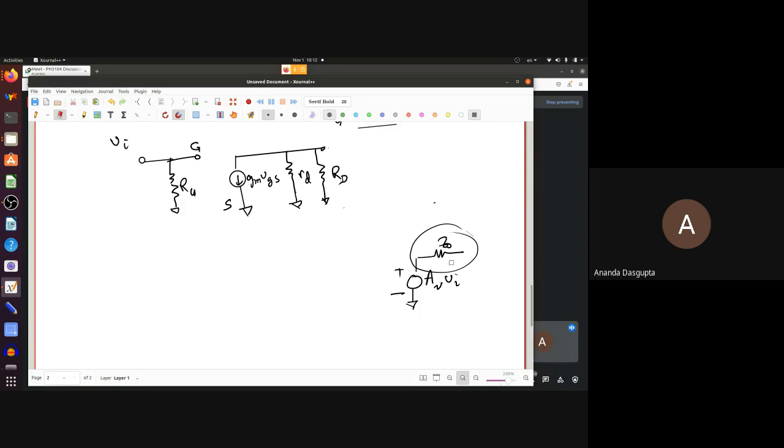Remember, this is just an effective circuit. It doesn't care what you have on this side. So you could also connect a voltage source here. If you connected a voltage source on this side, a Vx, some voltage source, and try to calculate the current Ix which flows in because of that, then Vx by Ix at Vi equal to 0 will give you ZO. In this case it's even easier, but still, let's go through the motions anyway.